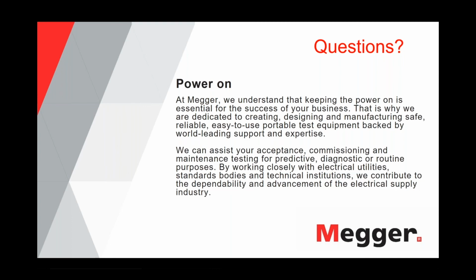On top of that, there's an asset management view on this as well, because you want to do the testing as much as necessary and as little as you can get away with. So it makes sense, because everybody wants to optimize where to put the money and how much money to spend. Now, on a service-aged cable, if you really have water treeing, the test that brings that out, first of all, to know it, would be the tan delta test, and then to have the go/no-go, that the insulation is still good for a certain amount of time, that is done with the VLF test.